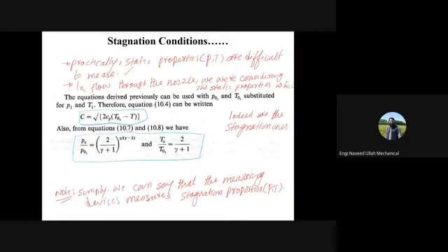I told you, whether it is the isentropic efficiency of the compressor, I gave you that example. Even if you look back to chapter 10, the initial slides, we were having these equations, 2 cp (T1 minus T). But here they are saying that indeed they are the stagnation ones.